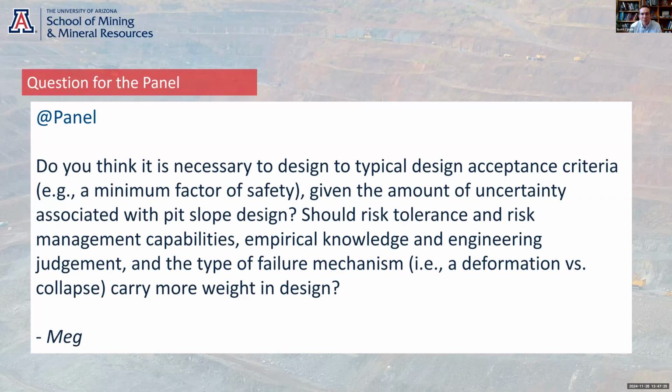So for any given slope, we might be analyzing 4 different things that could happen, 4 different types of failures. Each of those might have their own factor of safety value, but then the one that gets reported generally to the stakeholders would be the lowest one of the different mechanisms that are analyzed. So I would argue that we are considering all those things and giving them a pretty good weight in the design as things stand now.